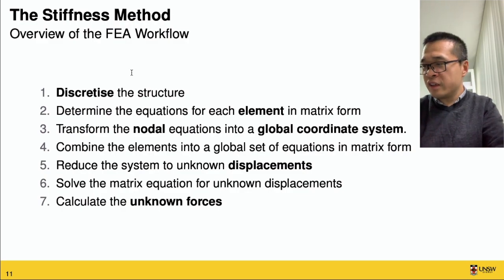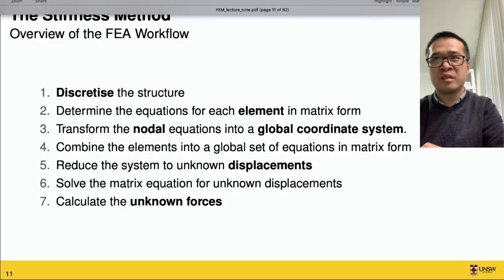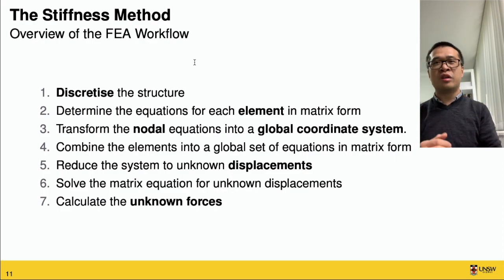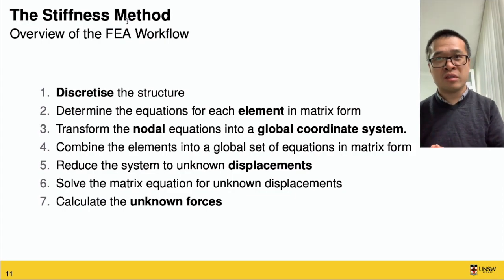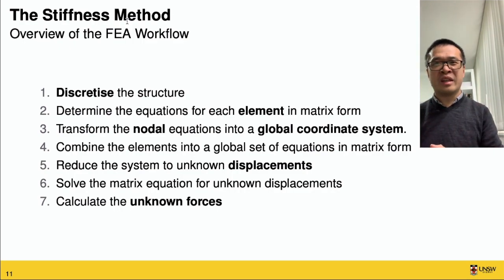Now, the whole finite element analysis is broken down into a workflow that we call the stiffness method. This works because we are treating everything linearly. That means when you apply a force to the material, it will deform linearly. This is what we're going to focus on in our course. Of course, when finite element analysis gets more and more difficult, it goes into a non-linear regime. That makes the whole thing more complicated, which we're not going to talk about in this class.